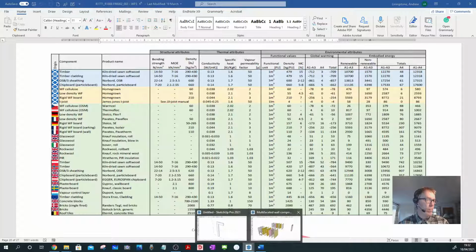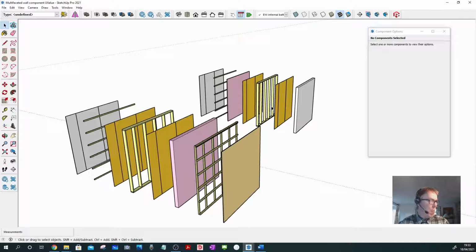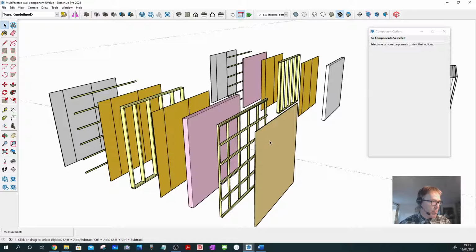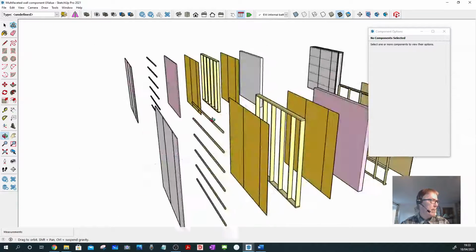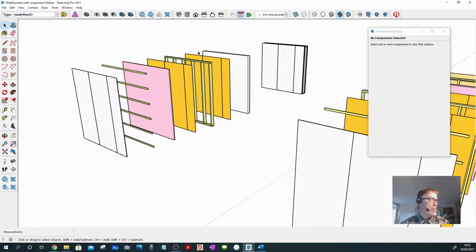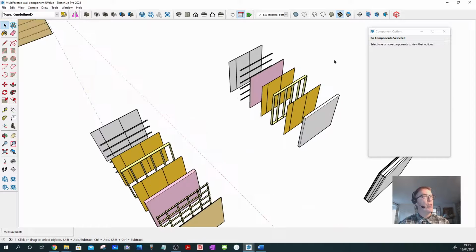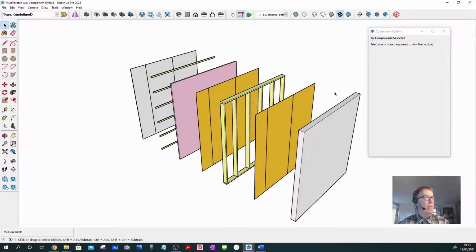And we're trying to create different types of walls, different types of floors and roofs and other elements as well. So we've done that. Just a quick example. This could be external timber cladding, vertical and horizontal battens, external insulation, timber frame with OSB both sides and insulation in the middle, horizontal battens for your services, and then your internal plasterboard. Or there's a brickwork type system instead. Again, timber frame, which you'll be more familiar with. There'll be a cavity in between.